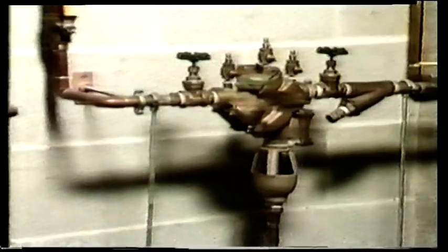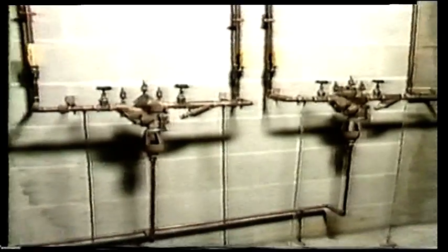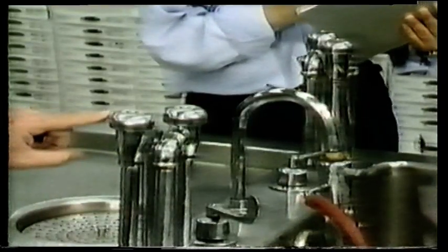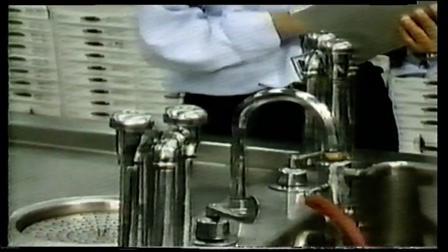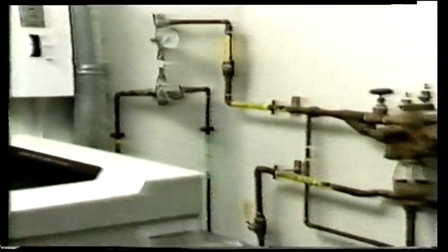First, the autopsy room, similar to the laboratory, is contained through internal protection by separate reduced pressure principle backflow prevention assemblies on the hot and cold water feeds and augmented by atmospheric vacuum breaker fixture outlet protection throughout the room. Second, in the radiology suite, the water feed to the X-ray developing equipment is protected by a reduced pressure principle backflow prevention assembly. Since both X-ray and autopsy represent high hazard areas, the choice of reduced pressure principle backflow prevention assemblies augmented by atmospheric vacuum breakers is appropriate. The survey team found this level of protection consistent throughout the other specific hazardous areas previously mentioned.